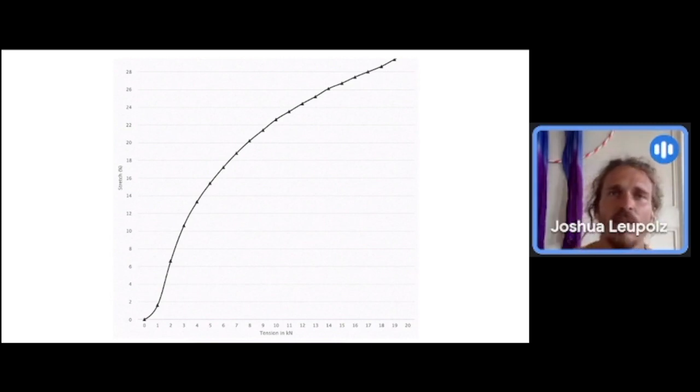And that's pretty interesting, because often if you want to calculate the forces going on during leash falls, you use this percentage of stretch. So you expect that in the leash fall you get forces of 5 kilonewton, so you stretch from 2.5 to 5 kilonewton. If you make the math and say the webbing is stretching 7%, which I get out of the graph, you can calculate the forces going on in the line, roughly.